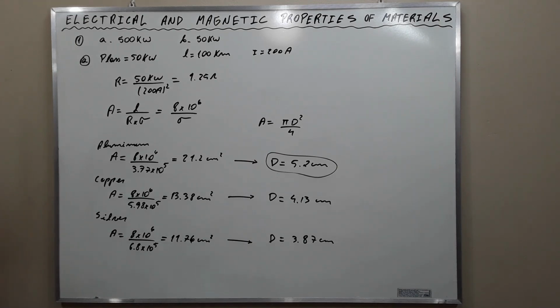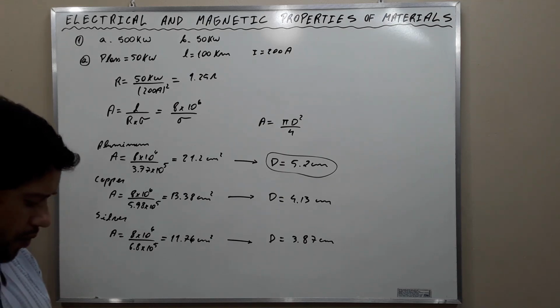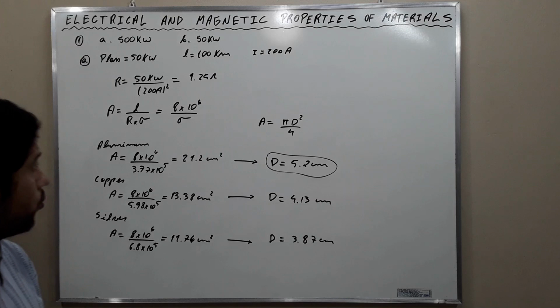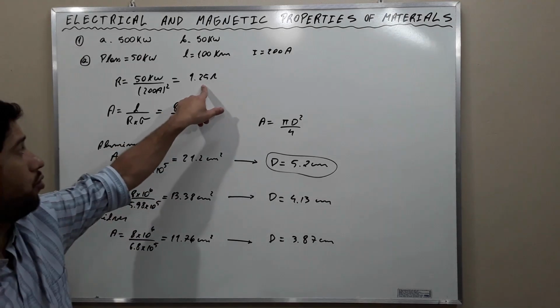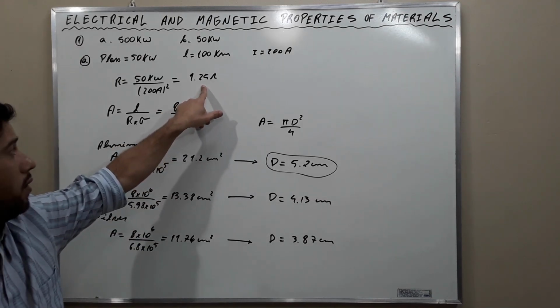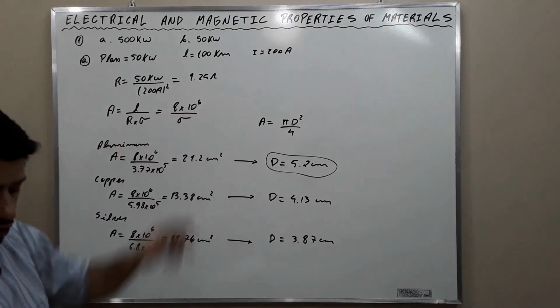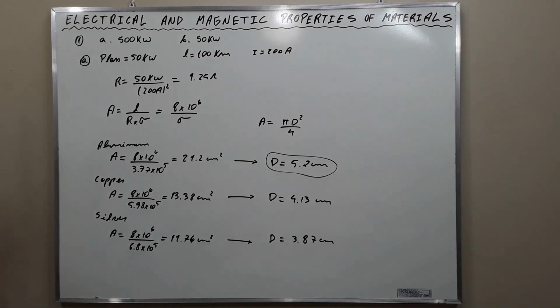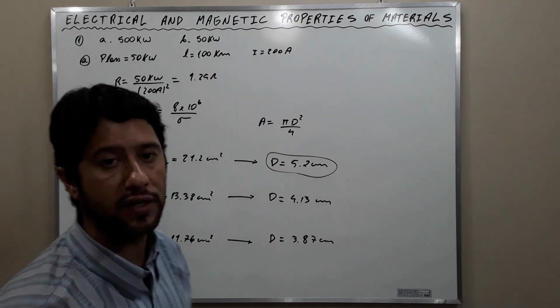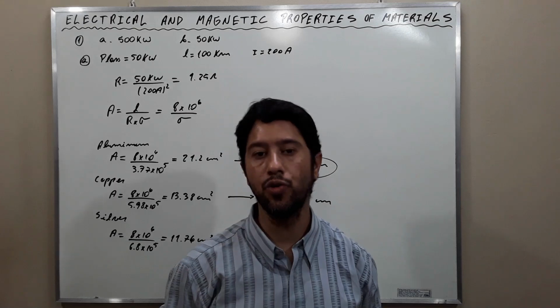So, what should we do? We should expect a larger power loss than 50 kilowatts over 100 kilometers of line and a cable with a resistance of a little larger than 1.25. This is too small, okay? Practical cables have resistances greater than this. Also, to avoid sagging, cables are reinforced with steel at their core. Alright, my friends, this was exercise 1. Let's go to exercise 2.